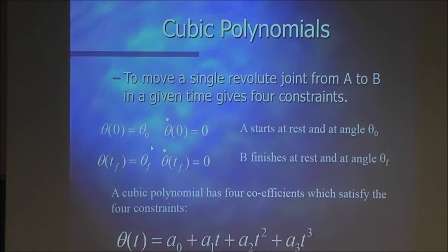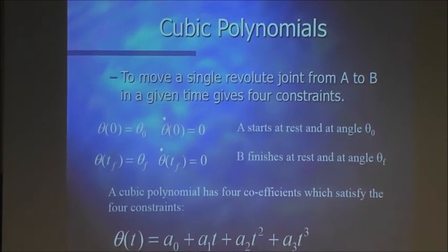You take the derivative of that, and because you know that the joint is going from a waypoint to another waypoint, it has to reach there, so the angle coming in has to be the same angle going out. And it also has to end up with 0 velocity at the end. Otherwise, you're going to break something. Okay? So all of those conditions are here.